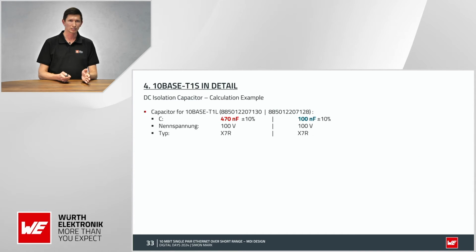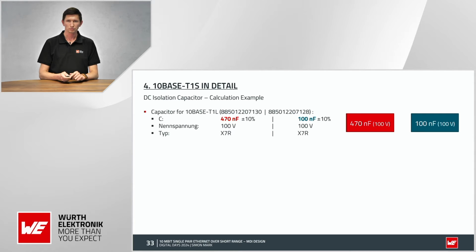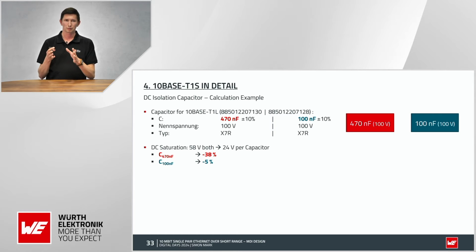I made a small calculation. It's a very rough calculation between 470 nanofarad and 100 nanofarad capacitors with the same voltage and the same type. After the DC saturation, so if you implement this 10BASE-T1L for a power over data line circuit, for the power over data line, we have also different webinars. You can look at them.